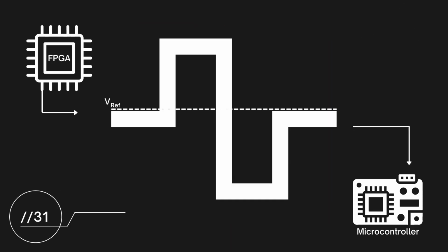No matter the oscillator's form, should the signal emitted from the FPGA cross the MCU's reference voltage, an interrupt event will be triggered. If the interrupt event is a rising edge, meaning the voltage started low then went high, we start an internal timer for 1 second, add an integer of 1 to our pulse counter in the microcontroller's memory buffer, then wait for and count subsequent rising edges. This is how the microcontroller is able to capture the FPGA's output signal frequency.